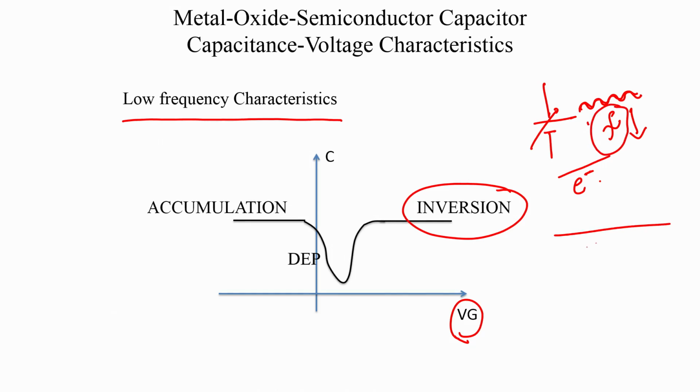So, you have an insulator, and you have firstly formed an inversion layer, and the frequency is low enough that when this charge goes up, thermally generated electrons can appear at the interface. The electrons are appearing and disappearing at the generation and recombination rates, and the generation rate is fast enough for the electrons to respond to this low frequency AC signal.